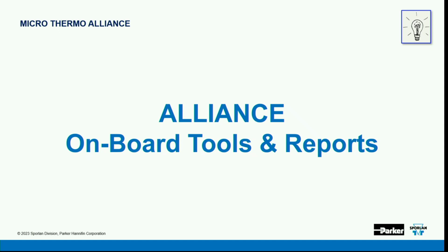Anything? Yes, sir. Sharing information from one node to the other, does it go through global like on other Emerson projects? What will they call it, global? That terminology is the same. We call it bindings, technically. That's what we use, bindings. But again, if it is a data point, if it's a superheat, if it's a pressure, if it's on the system, any node could be told, listen to this input. It's important to you, okay? Or we could tell it not to listen to it, if we don't want too much information. So if it's on the network, it's shareable to any node that's on there.